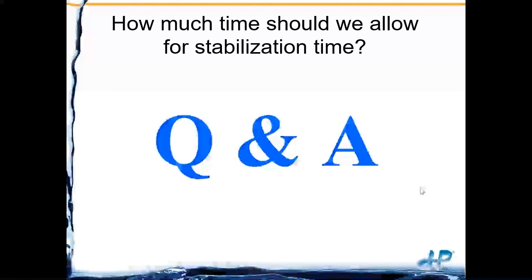About how much time should we allow for stabilization time? Depending on your solution, if you have cleaned it with something that's strongly oxidizing or strongly reducing, that 30-minute window is a good rule of thumb. If you've done that and then you put it in your ORP solution, I would say no more than 2 to 5 minutes is probably what's needed for an ORP electrode, unless we haven't cleaned it. Over that, we're going to probably need to clean it, because these should be a lot quicker calibrations than what we see with pH, because it's just a piece of metal.